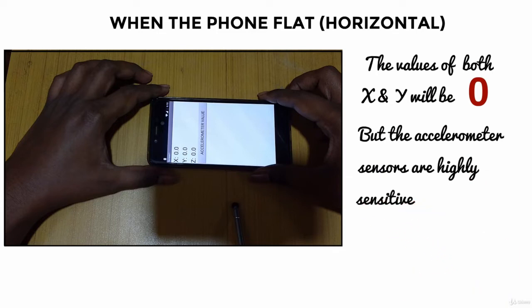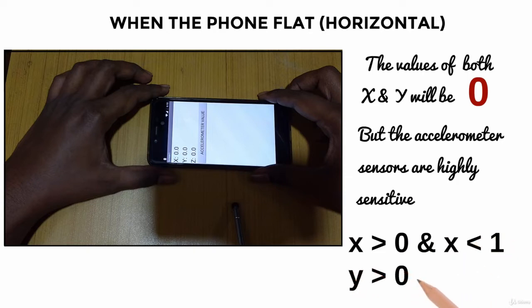So for the stop condition, instead of using a single value, we will use a range between X and Y. That is X greater than 0 and X less than 1. And on the Y side, we will take Y greater than 0 and Y less than 1. So guys, when we take this condition, then even if you tilt your phone by a small angle, the robot will not move.